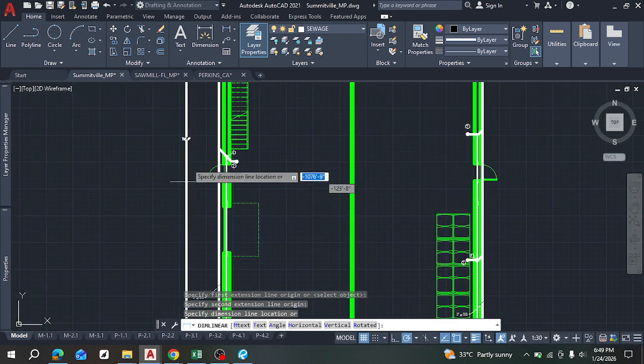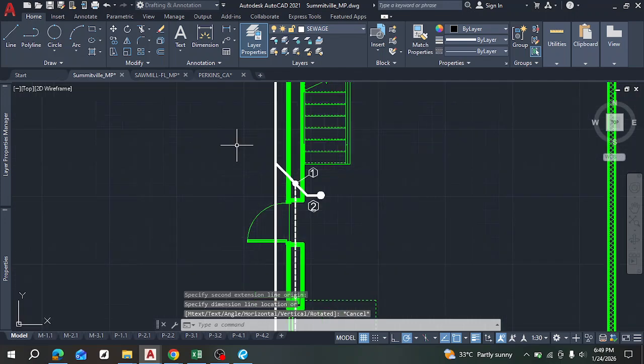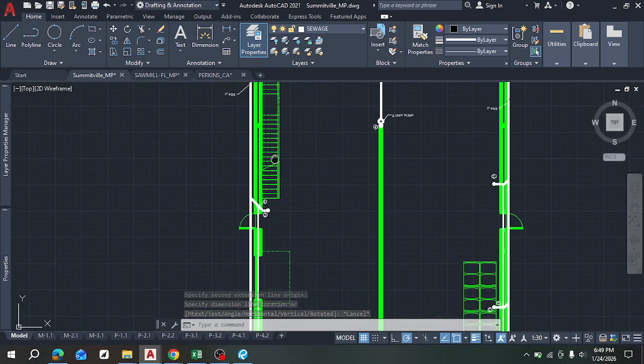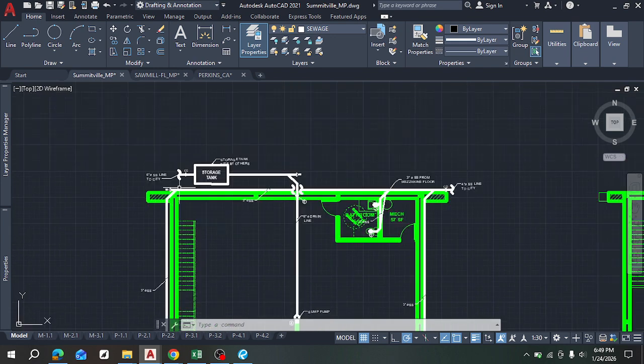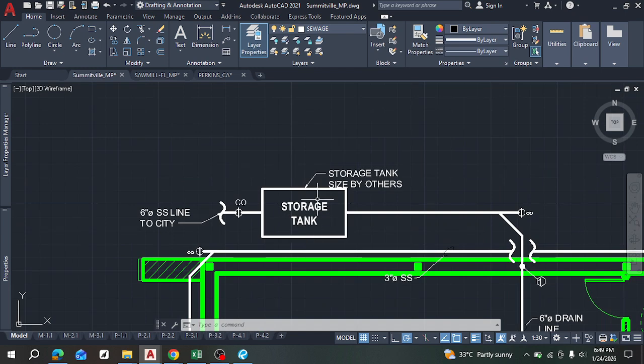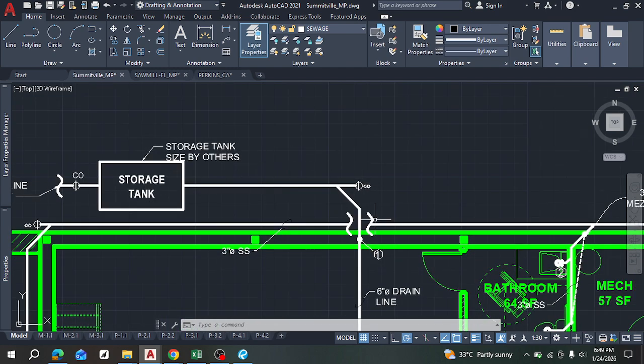See, it's almost up to 100. So I mean, fair point. There are larger buildings where it could be way more. So that's where the clean out comes in, right? So use your discretion to add it. Now this storage tank, I'm not the one sizing it, thankfully, right? But I'm sure if you do a bit of research on either international plumbing codes or, this is a California project, you'll be able to find something that can enable you to understand how this sizing takes place, right?